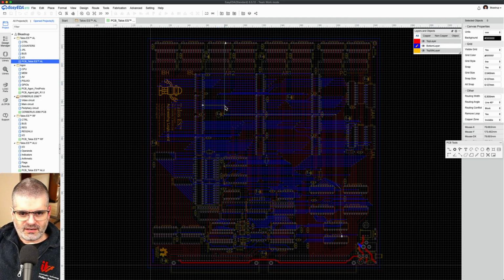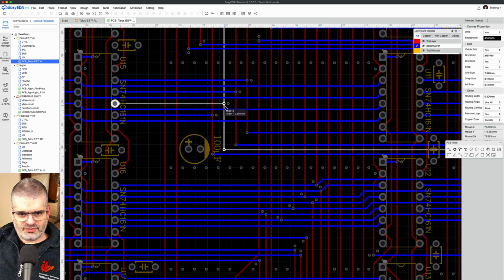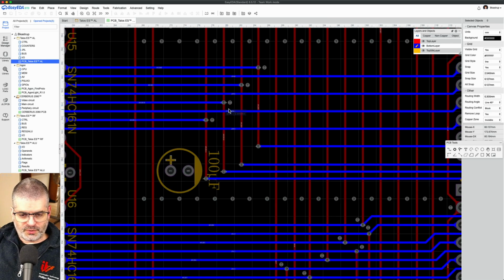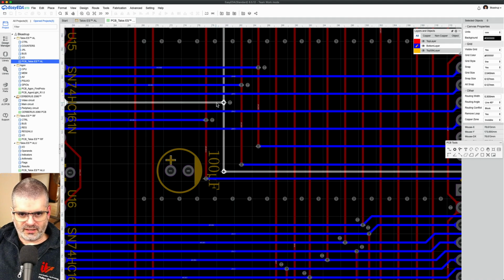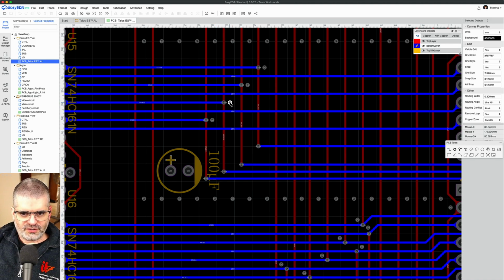And I'm being very careful about always using these transfer vias and return path vias, and in this case they work as both, because I'm using planes now. When I go from the top layer in red to the bottom layer in blue, I'm changing the reference plane from ground to VCC, so we need a transfer via to keep the field fringes tight as we move from one reference plane to the other. And they also provide a return path for the return current to ground. So I'm very assiduously using these return path vias.